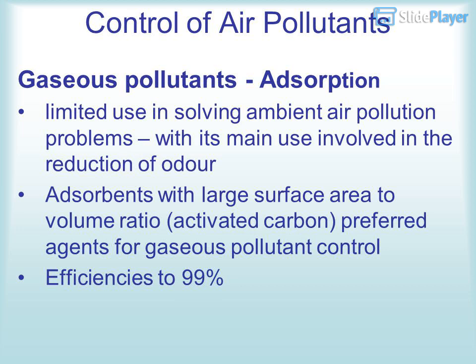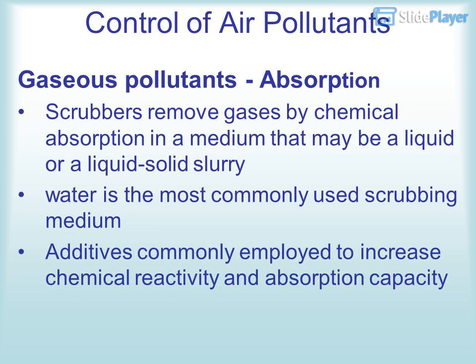Control of air pollutants. Gaseous pollutants, adsorption. Limited use in solving ambient air pollution problems, with its main use involved in the reduction of odor. Adsorbents with a large surface area to volume ratio, such as activated carbon, are the preferred agents for gaseous pollutant control. Efficiencies to 99%.